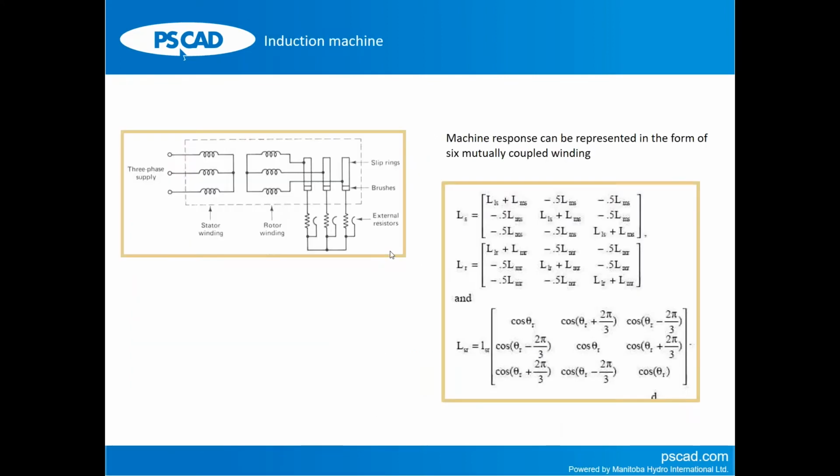Induction machine, like the concepts are similar. You have the three-phase windings, you have three rotor windings that are not supplied or connected to, in general, if it is a wound rotor or a squirrel cage operating in normal applications. You don't connect the rotor to a supply or DC field or supply, right? You just short it, right? So you have three windings and three shorted windings.